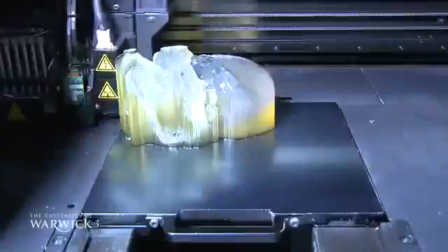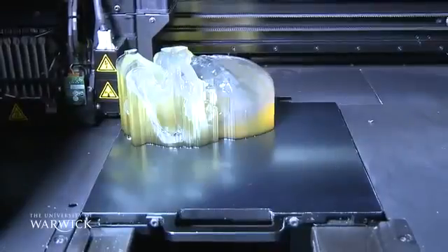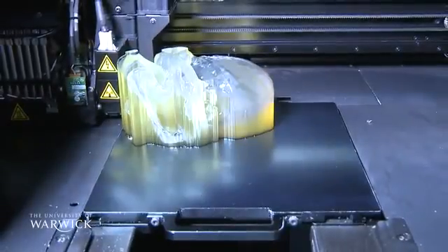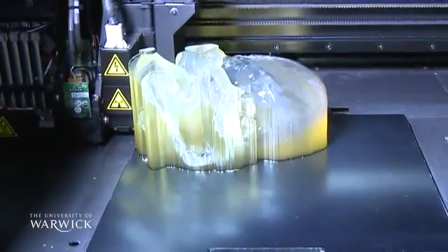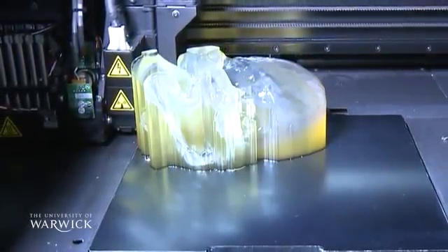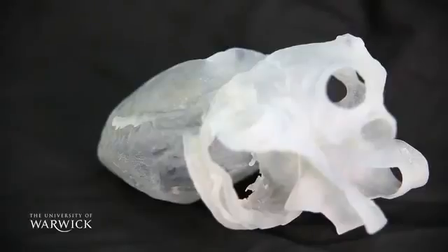Well, we've got a number of heads, so some print out the build material, which will be your final part, and some print out a support material, which, because it's coming out as liquid, it needs somewhere to land. So the layers are 30 microns thick, so each layer adds 30 microns of the part. It keeps doing this from the bottom to the top of the part. When it's finished, you'll have your part embedded into a gel-like support structure, which we then remove using a water jetting process. The difference with this printing is that it had to be transparent.